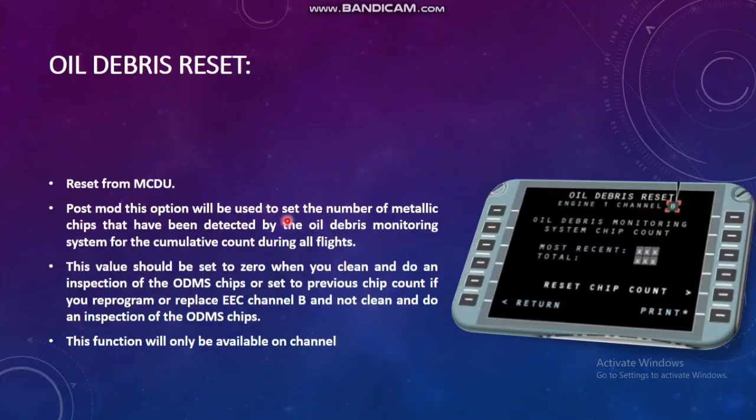This option is used to set the number of metallic chips that have been detected by the oil debris monitoring system for the communicated count during all the flight. Post mode in all flight, and this can be reset from the MCDU. So we'll not go through it again.